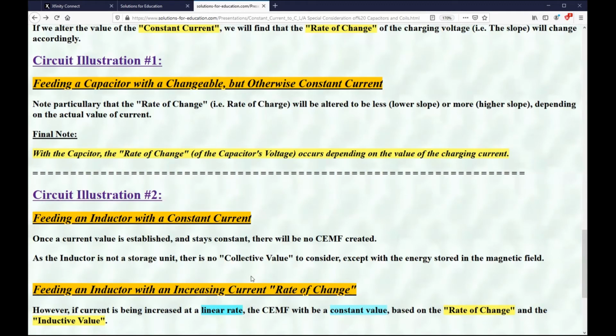And if that time is very, very short, you can take what is normally a 5 or 6 volt circuit and develop a couple thousand volts. The formula is called E equals dΦ/dt. I thought about putting that in here with the Greek symbols, but I decided, okay. All right. The inductor is not a storage unit, well, wait a minute. It's not a storage like a capacitor.